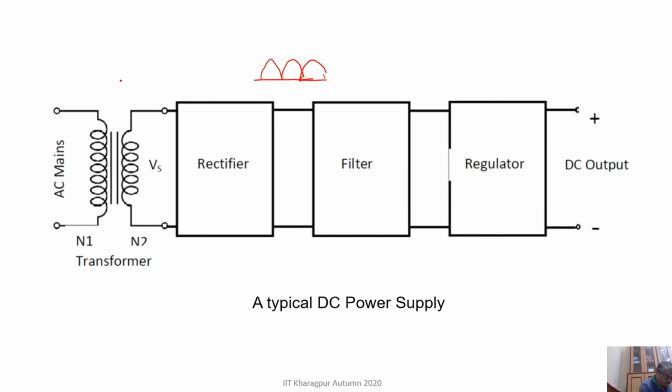So what we have done, we can apply a filter circuit in the form of a capacitor and resistor to improve the circuit performance. And what we get is much less ripple at the output of the filter compared to if I measure ripple here.